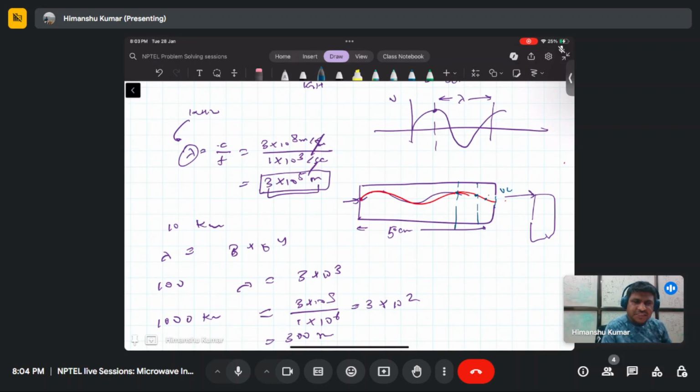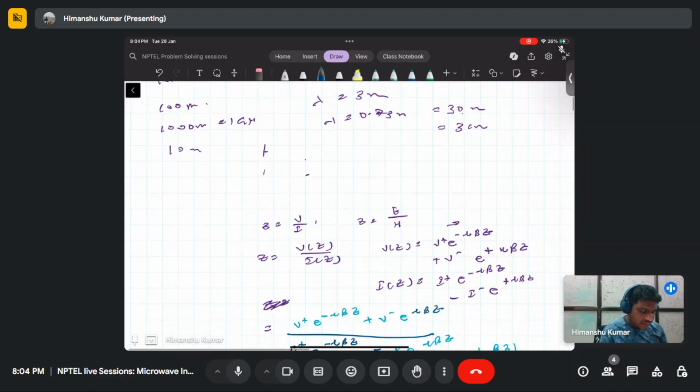As you can see, even a minor change in the length of the line gives a different voltage, and if you are driving a load of fixed resistance, that will lead to a different current. So even a minor change in your line length makes the power transfer to this load variable. That will lead to reflections in the case of high frequency.